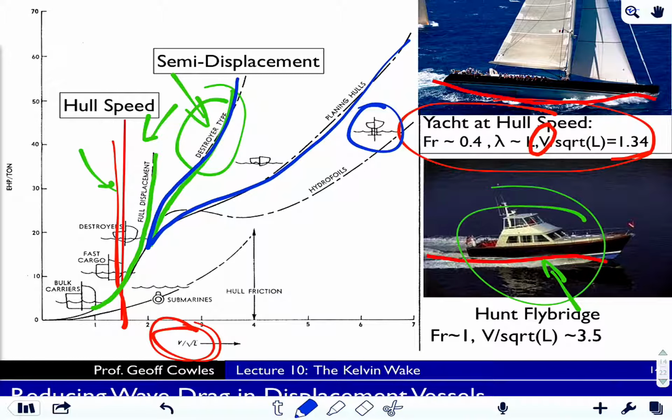Well, not zero impact, but almost no impact because it's in the air. And now you're dealing with overcoming drag on the foils, which are lifting bodies. So that's induced drag and friction drag on the foils. And in some hydrofoils, not all, you actually go through a point, like a ferry, where you are pushing, you're in a steep part of the resistance curve, then it starts to foil because you're going fast enough.